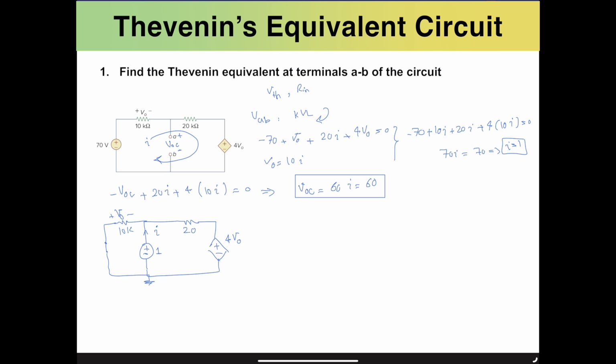So in order to do that, we would consider that I is going up, and that helps us to make use of a KCL at this node. We just then need to find out what are the currents on all the other branches. For instance, what is the current passing through this resistor? We already know the voltage drop across that, VO from the left to the right, which helps to get to the current of VO divided by 10K.